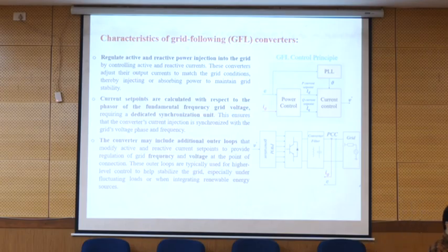For example, if a fault happens, the fault ride through capability is something we should consider in the control loop of the converter. For this reason, only considering the current control loop for that type of converter is not enough for the power grid. You have one option to just inject into the distribution power station, but if you are going to connect to the load center, then some extra features are also needed. Any questions so far?